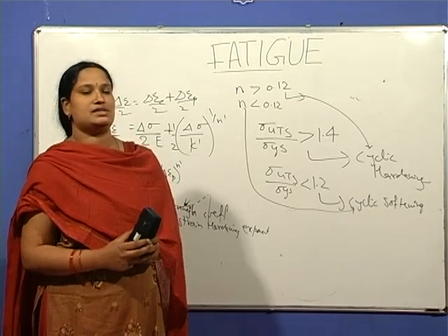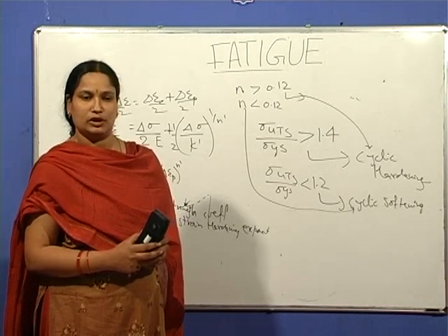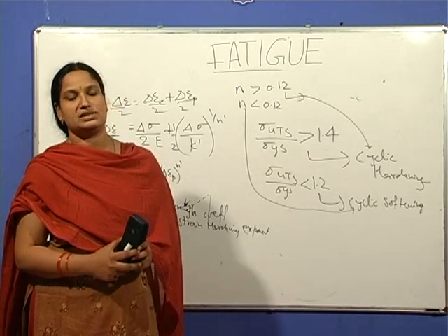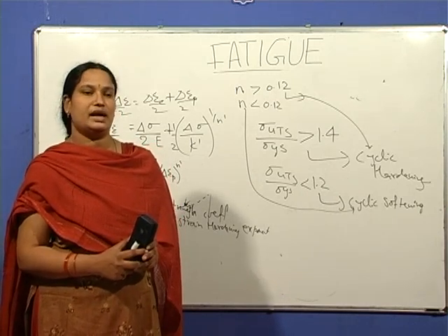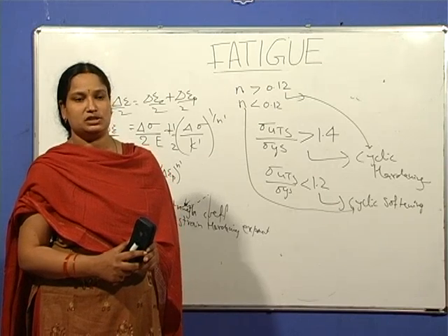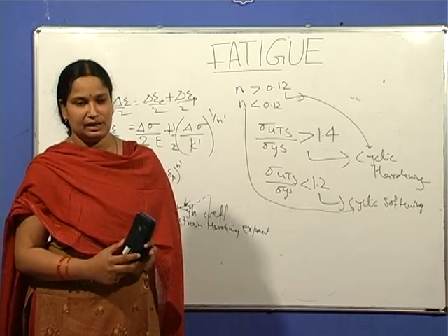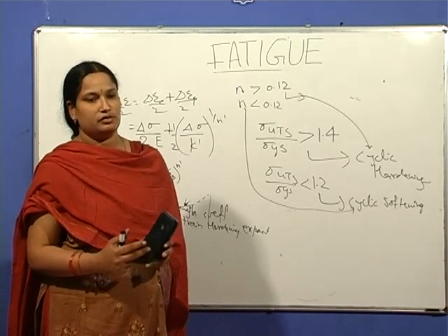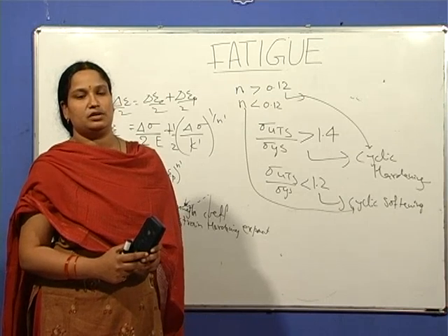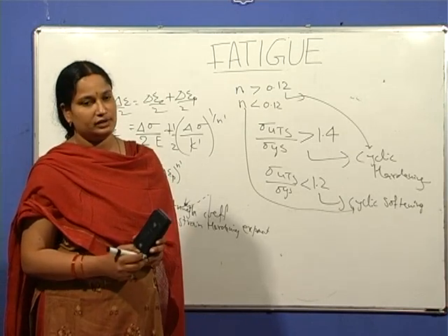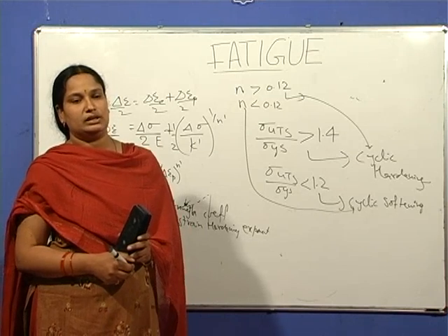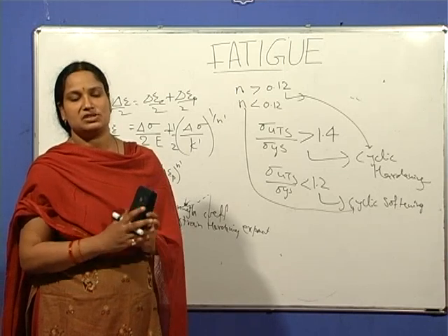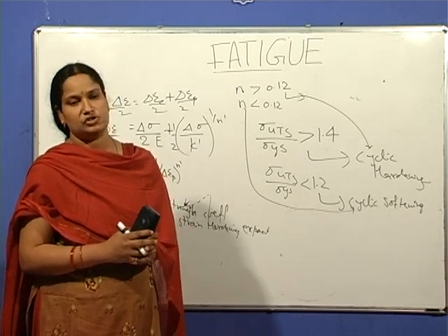The origin of stresses in the case of low cycle fatigue is mainly thermal, whereas in the case of high cycle fatigue it is mechanical. Most components in high temperature applications are subjected to repeated thermal cycling because of variations in temperature, due to which thermal stresses are developed, because the component is not free to expand and contract freely. Thereby strains are induced in that material, causing thermal strains.